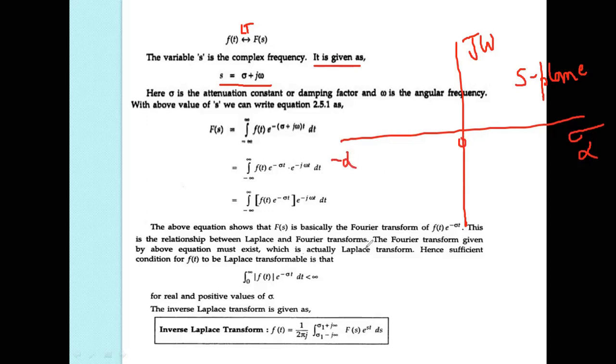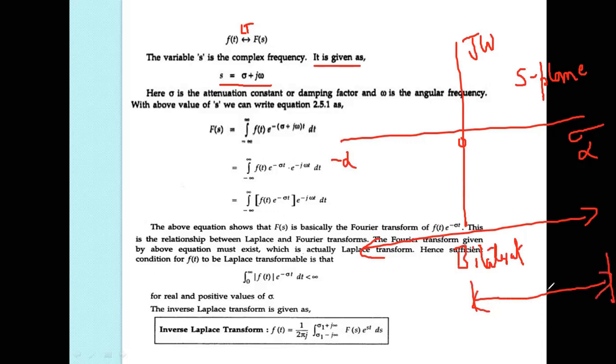So the bilateral is totally common, the bilateral Laplace transform. And only if I am taking the single-sided, it is a unilateral signal. What is that s? S is nothing but sigma plus j omega, a complex frequency. The real term is sigma and the imaginary term is omega.